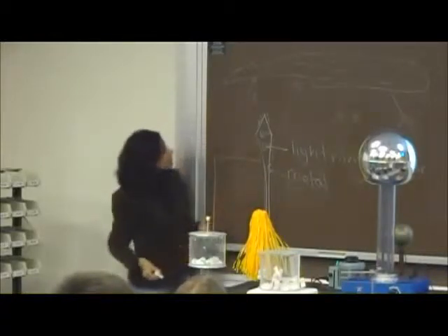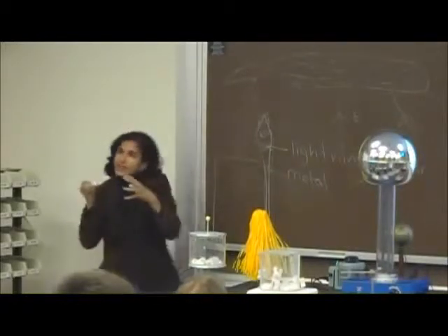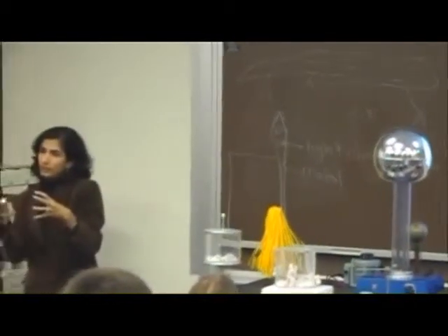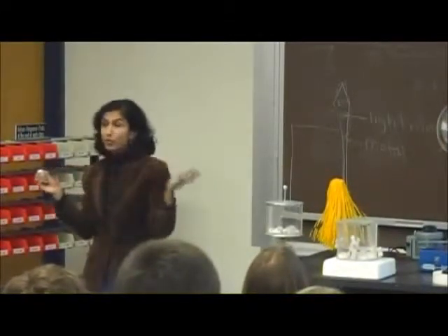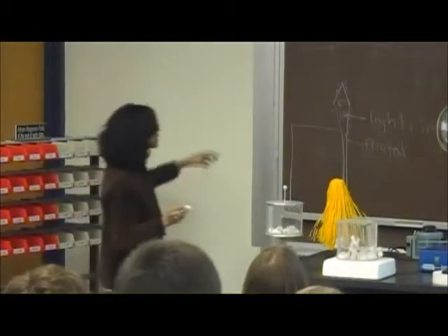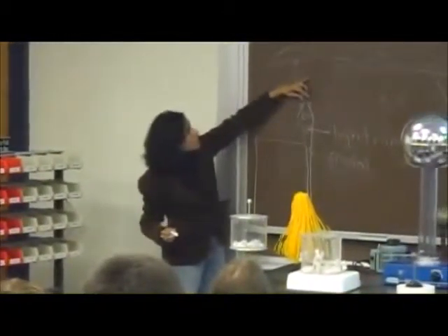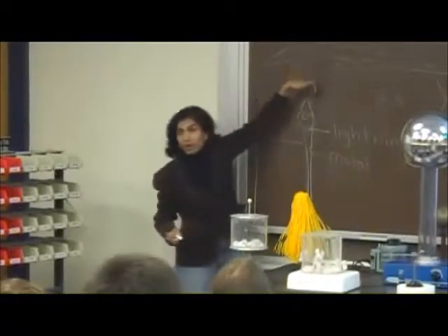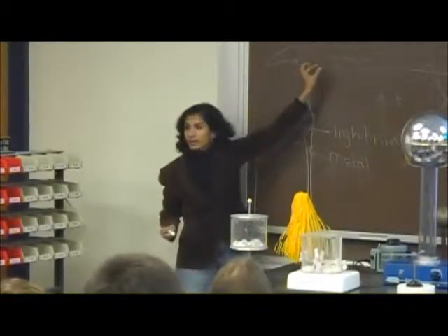Now here is the thing: at the pointy edge, the charge density will be largest, much higher than at other places. So if sigma is largest at the pointy edge, then the electrical breakdown of the air will happen first in this region.